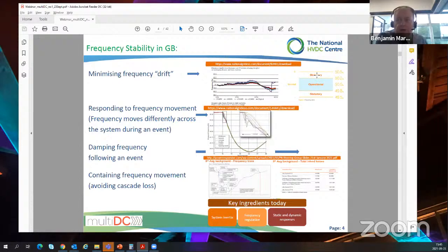The latter approach of using those large load banks gives you a national view. The former, using PMUs, can give you an idea of your distribution of inertia, which, in understanding the differential nature of your frequency following an event, becomes quite important. If we move to the next slide then.